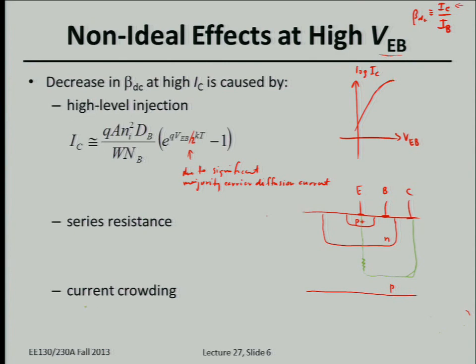Okay, another thing that's interesting in a bipolar junction transistor is that, well, here's your base emitter junction, right? It's here. So technically, current can flow anywhere between the P plus and N regions, and between the N and P regions, like along the sides of the junctions as well as the bottom. So what happens is that as, let's say, holes are injected into the base region, they can spread out.